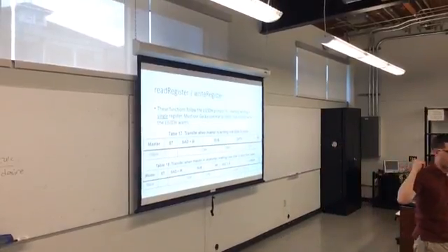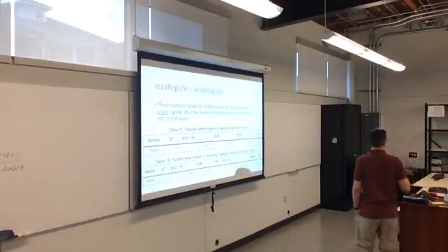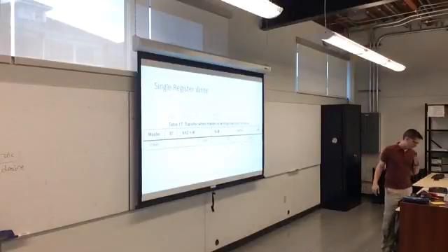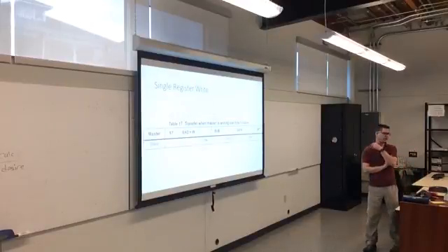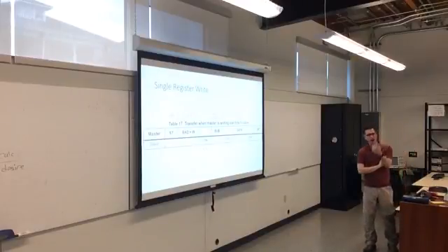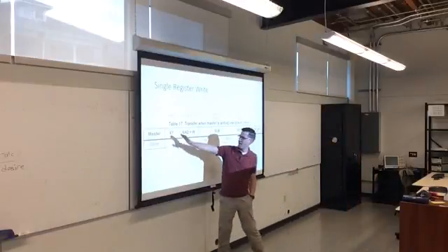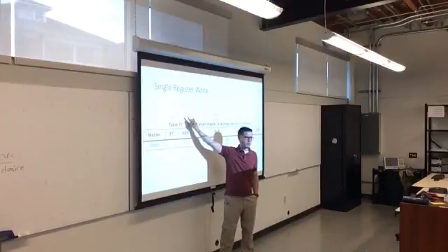So the way that you want to interpret this is that if you're going to do a write, if you want to write to a register on the accelerometer, the master has to send a start bit along with the accelerometer's address and a write bit. If he gets it, he will then acknowledge. Once the transaction's been set up, the master will then send the register address that he wants to write to.